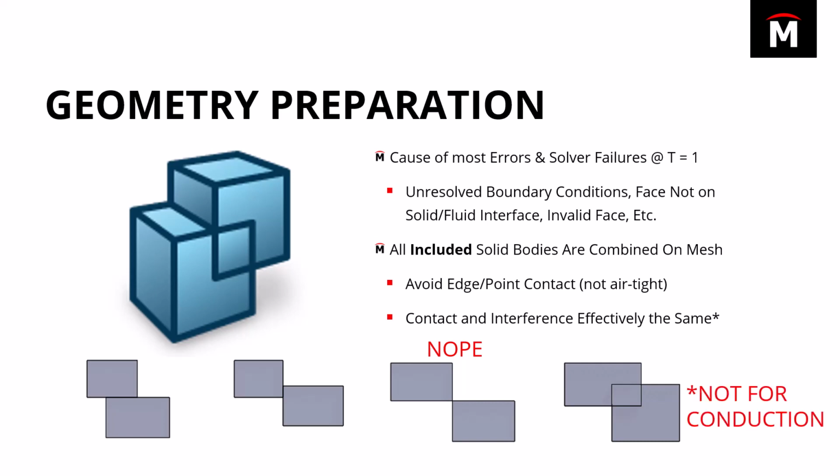The interference fit, which is how most lids are created, is totally fine for the majority of things except for conduction. Main reason being, you don't know the density, the thermal conductivity, and everything else if these are two different materials and they have an interfering volume. So that's the only thing that could cause some weird results. Otherwise, just anything, as long as it's airtight, is going to close that volume in.